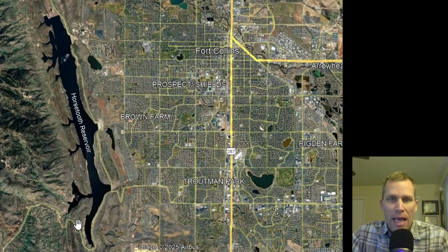Well, what I did in that video was use a geographic coordinate system, and what I realized is that ResSim works with projected coordinate systems better than geographic. I'm not totally convinced that it even works at all with geographic coordinate systems, and I'll show you why a little bit later in the video. So I wanted to do this follow-up video to explain how I would export my shapefiles from QGIS and how I would import them into HEC ResSim in order to preserve the size and shape properly.